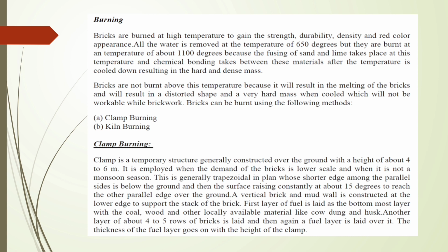While the water is removed at a temperature of 650 degrees, the bricks are burnt at a temperature of about 1100 degrees, because the fusing of sand and lime takes place at this temperature and chemical bonding takes place between these materials. After the temperature is cooled down, this results in a hard and dense mass.